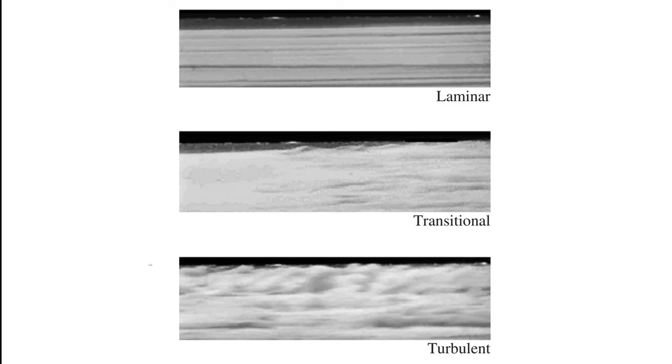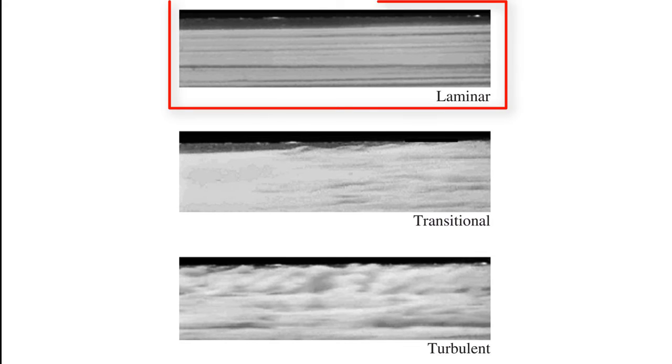Now I talk about laminar versus turbulent flow. Some flows are smooth and orderly while others are rather chaotic. The highly ordered fluid motion characterized by smooth layers of fluid is called laminar. The word laminar comes from the movement of adjacent fluid particles together in laminates. The flow of high viscosity fluids such as oils at low velocities is typically laminar.